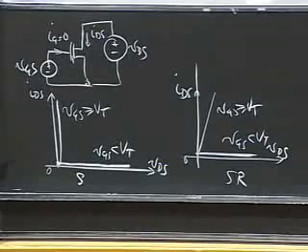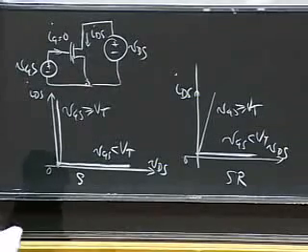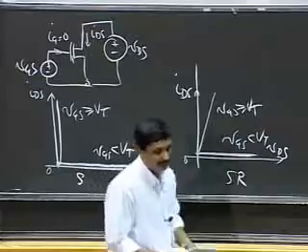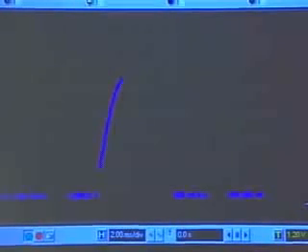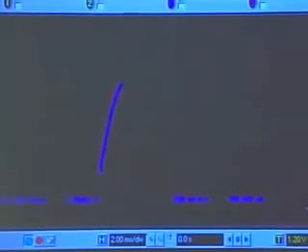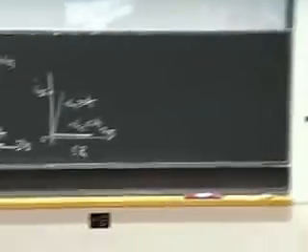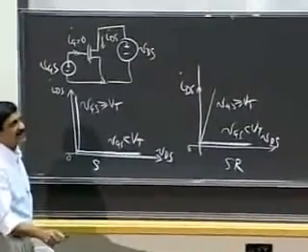Now what I've plotted there for you is that behavior, up here. Notice that this is the VDS axis and this is the IDS axis. I'm plotting IDS versus VDS. And when VGS, the gate voltage, is more than a threshold, notice that I see what looks more or less like a straight line, with some slope, implying resistive behavior.